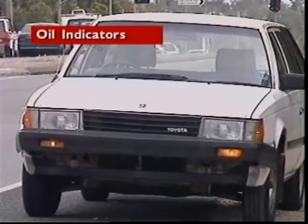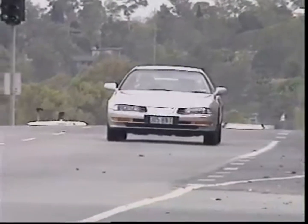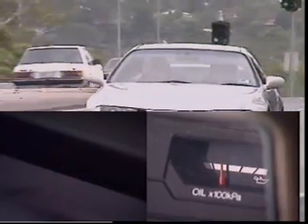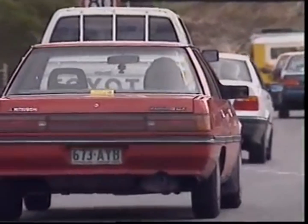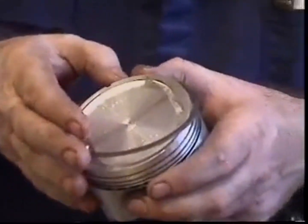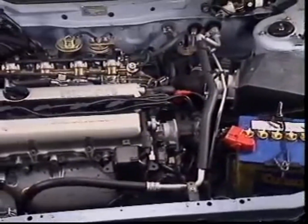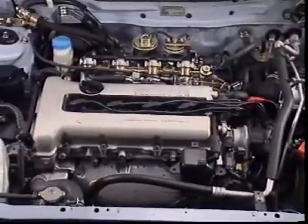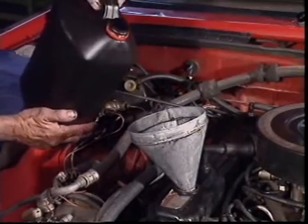If a lubrication system fails, it's serious, so it's crucial to know it's working. If oil pressure falls too low, a pressure sensor in a gallery can light up a warning light or register on a gauge. Low oil pressure can mean a lack of oil. It may have leaked away, or it may have been burned. This can be caused by worn piston rings which let oil into the combustion chamber. Some engines even use an automatic cutout that turns off the engine if oil pressure falls too low.